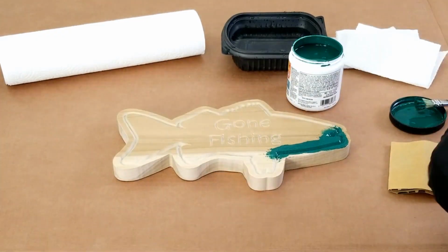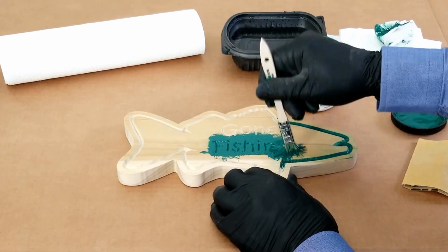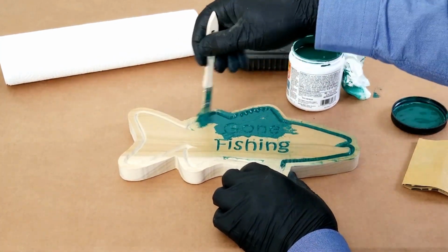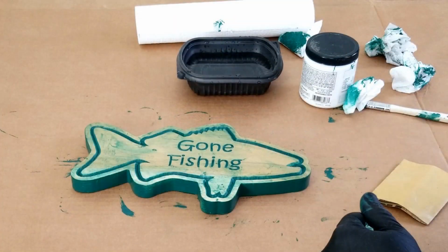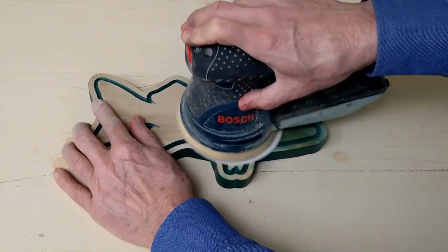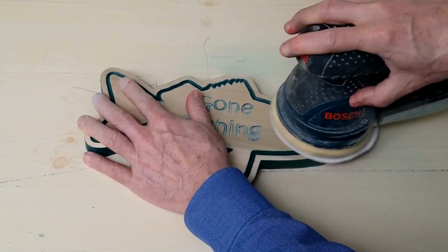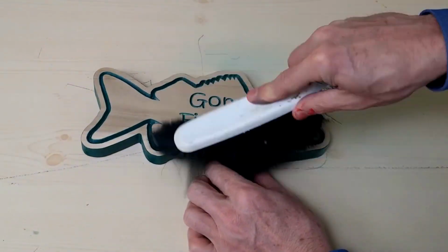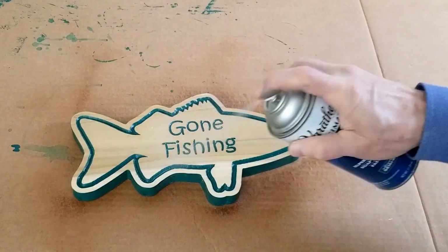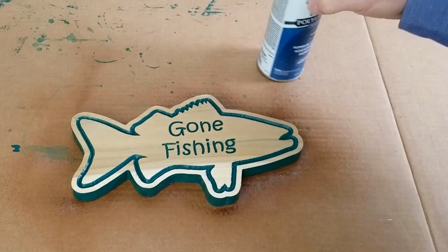Next up, I'm going to add a little bit of finish to it. I'm simply going to brush some green paint into that groove and then use a paper towel to rub most of it off. I'm not really too concerned about the amount of paint that's left on the surface because I pre-finished it. When it comes time to sand it off, the sanding goes very quickly, and that's one of the reasons I did the pre-finish. It prevents the green paint from soaking into the grain and leaves a much cleaner finish. It also makes the sanding easier. When that's done, a couple coats of clear finish and the project is complete.